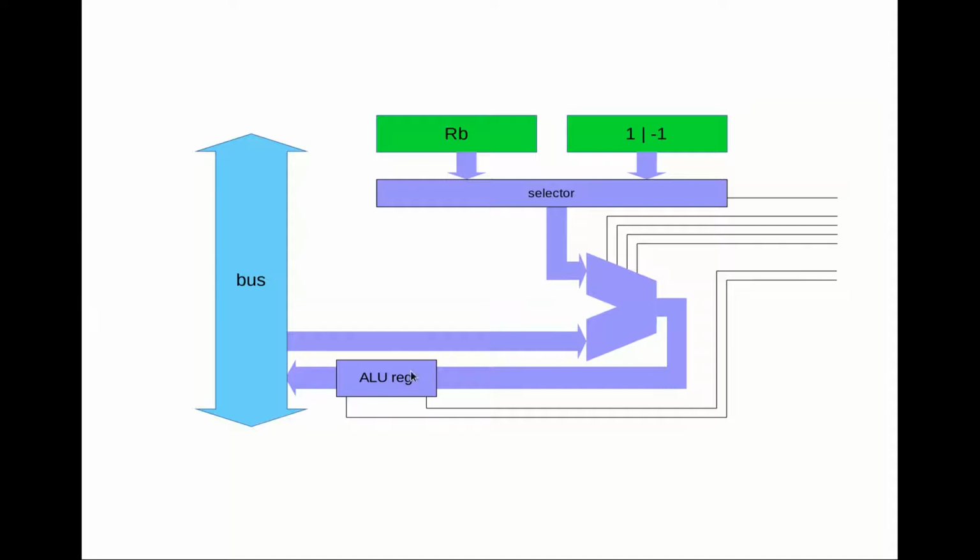And it's going to do that while the A register up here is still asserting its contents onto the bus to make sure that that ALU is in a valid state and adding two well-known values, in this case A and B, and therefore that the result of this addition is a well-known value, and that will get latched into that register in one step.